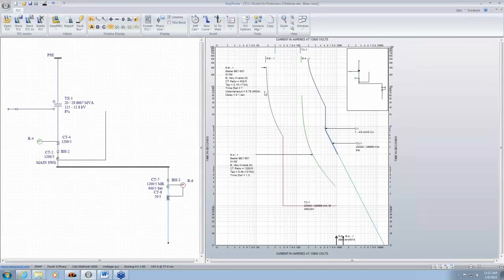If you look at the relay curve, there's just a very thin line, and that's been the practice for a long, long time, so it does not have margins for tolerance. Fuse curves, solid state trips and thermomagnetic breaker curves had a tolerance, a very thick band, which accounted for minimum and maximum clearing. In relays, that's not the case.